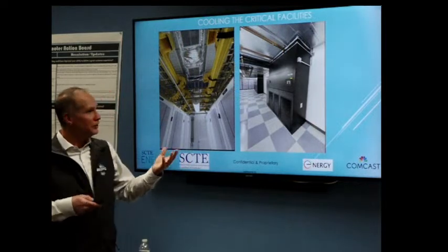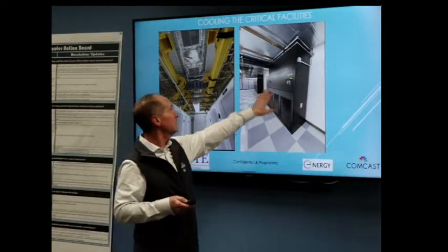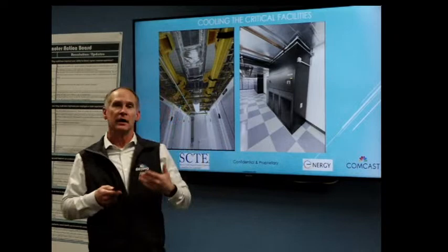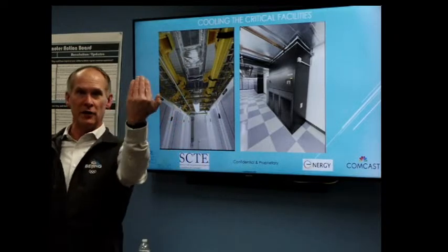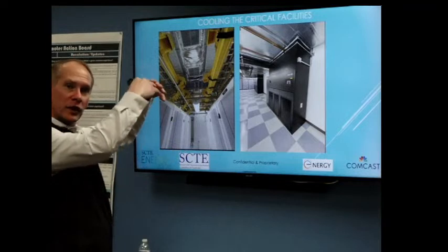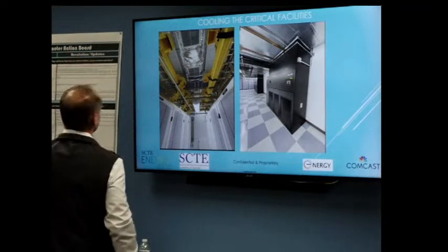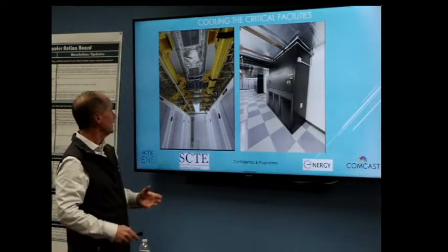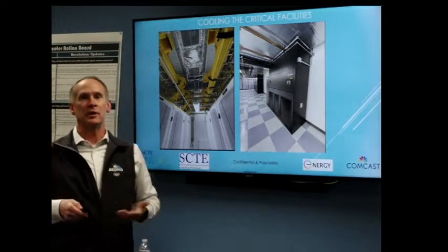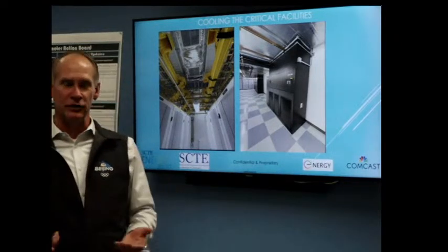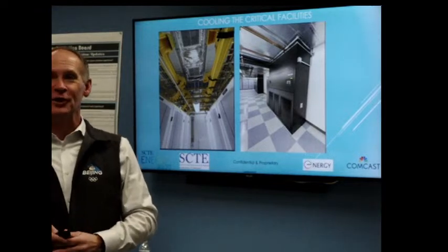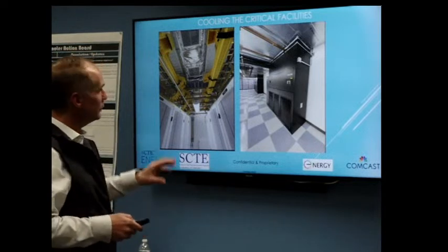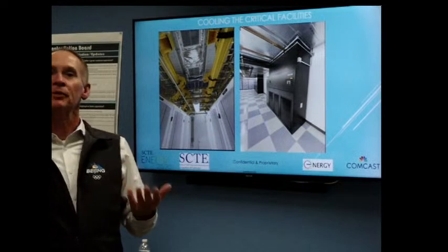As you can see on the inside, now you've got a few different flavors. You have a ducted system through these CRAC units. They're going on what's called an upflow system. The upflow system allows fans to push air up the ductwork, over through your infrastructure, through your building, and then be placed in a cold aisle environment through the ductwork that is able to shoot down in front of it. This is a good technique. It's a ducted technique. People have used ducted techniques for hundreds of years. You have a ducted technique in your own house. I don't know anybody that really uses a flooded system in your own house because it's just not efficient. But what this does do is it starts to layer in a level of complexity.